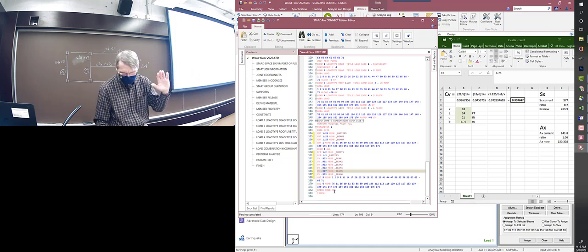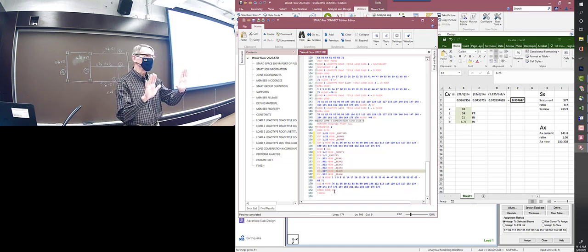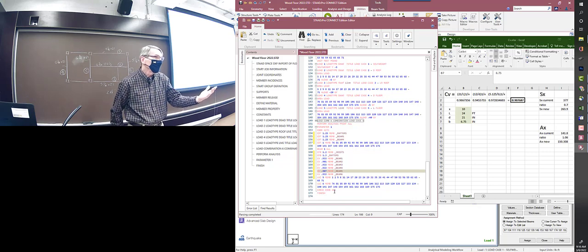And you can see, I'm not going to keep doing this over and over again, but your goal would be to try to get efficient members for each one, nothing failing, and try to lower the utility ratio to something reasonable, like 0.8. Ultimately what you try to do is pick the smallest member, right?